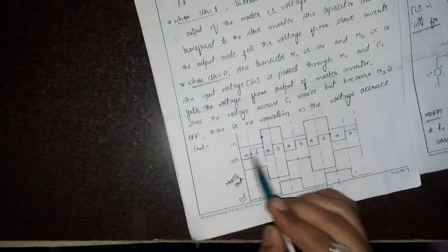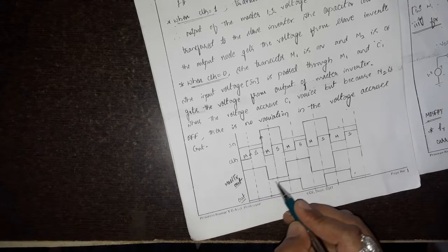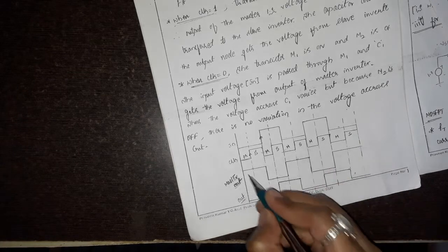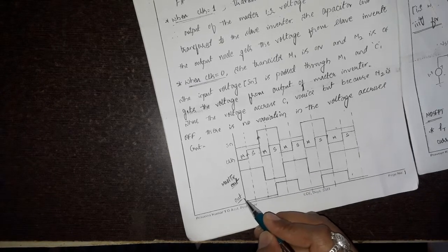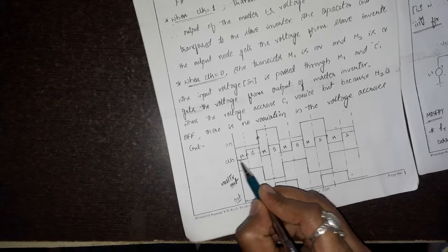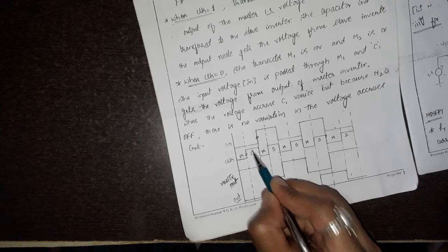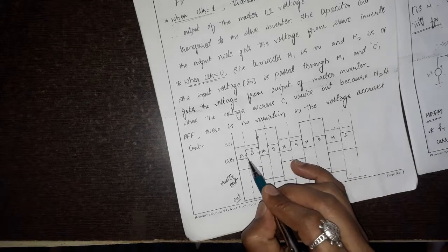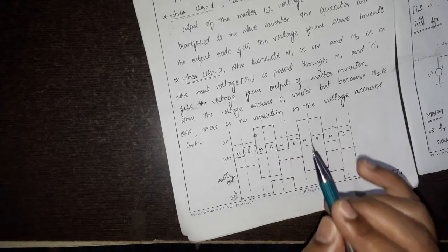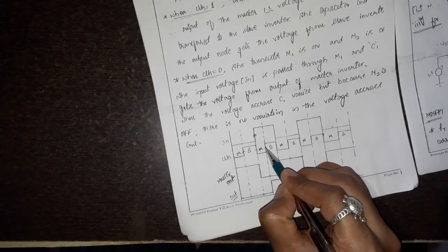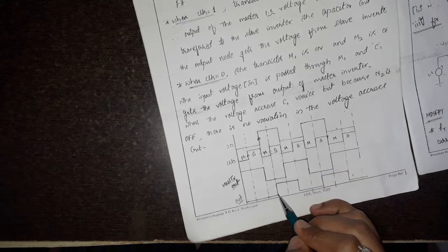where in the waveform you can observe that this is the input signal, the second signal is the clock signal, the third signal is the master output or the voltage across the C1 capacitor, and the fourth signal represents the output signal. And it could be observed that when clock is logic 0, master will be in active state. When clock is 1, slave is in active condition, and whenever the slave is in active mode, the output represents the delayed version of the input. Observe here, during this phase slave is active, so output is nothing but the delayed version